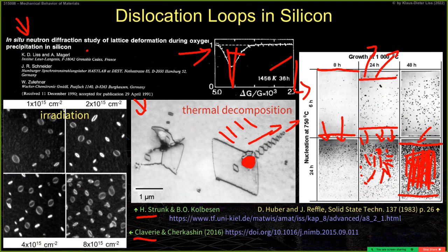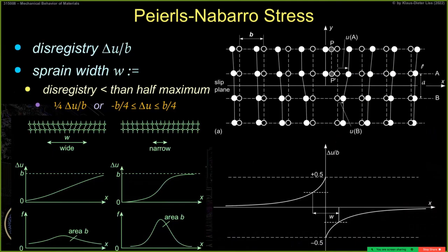So they get bound in the strain field. That means at the surface we also get depletion of other impurity atoms. So this is an industrial application of using dislocation loops in perfect crystal silicon to make the surface even more perfect in terms of solid solution atoms.